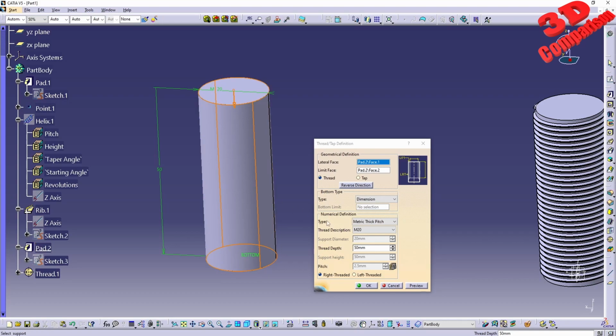As you can see over here, if you want to do a design that we afterwards want to maybe 3D print, we will have to do that manually since CATIA only has the thread definition, which will be schematic and which will be positioned onto the 2D technical drawing. But there's no actual geometry being created. So if you want to make a working prototype, you will have to model it yourself.